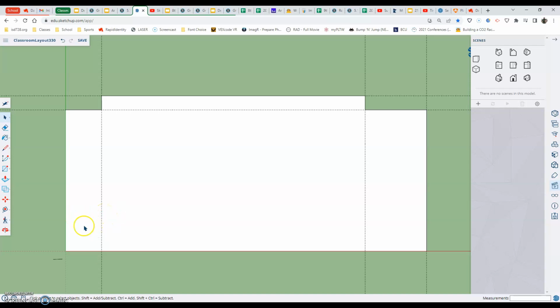The one thing I do want to check before I leave here is just my dimensions. Make sure they're right. So going into my tape measure, I want to select the dimension tool. I want to select the edges that I just made, click on them, slide out, drop them. And I want to do that for all of my dimensions. I need to check just to make sure that I entered things correctly. And I didn't use that 48 inches, but it's nice to know. And then the other thing is 2'8", and then the bottom overall. Once I have all my dimensions pulled and I check to make sure that they're the right things, I should be good to go and ready for the next video.